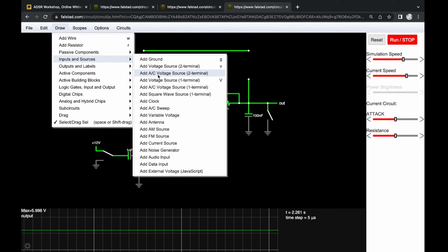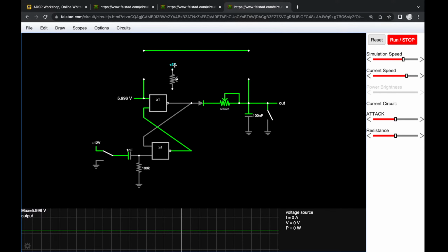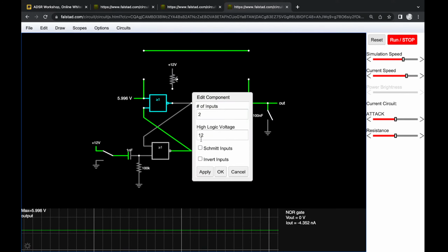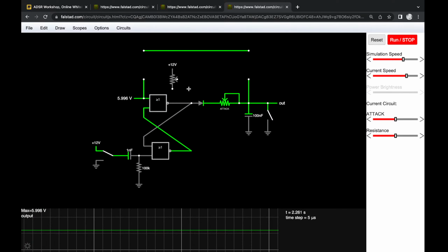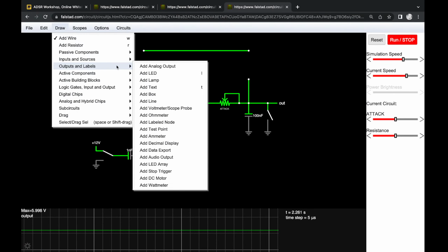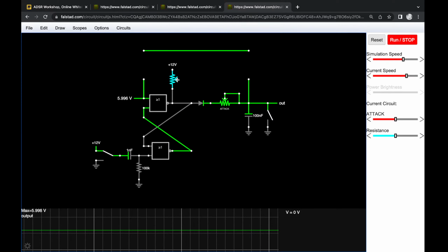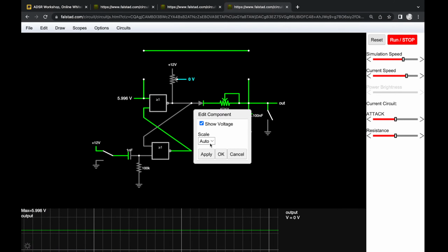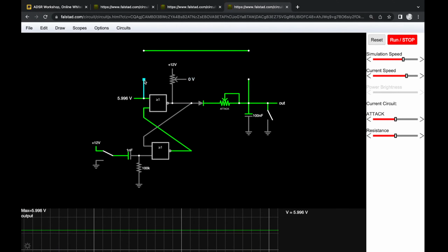Then we'll place this between a voltage source. So we go with our supply voltage, which is, as you remember, 12 volts. You can do this with any other voltage level, whatever you want to use. You can use 9 volts, you can use 15 volts, doesn't matter. So we're going to set this up between 12 volts and the output of our SR flip-flop. And let me get the analog output here so that I can show you what the voltage here is going to be. All right, I need to connect this again, and I need to connect this again. Whoops.